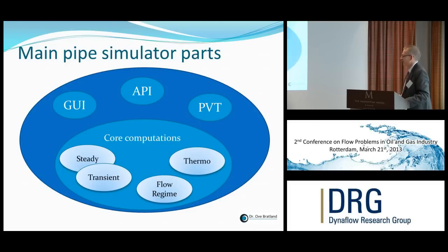It has to determine which flow regime they have, and that's what they are least good at, I think. It's difficult to do that accurately. Do you have slugs or not? Do you have stratified flow? What do you have in there? How does it flow in there? And they also handle PVT properties differently. They talk to third-party software, at least that's what Olga does, and take chemical properties from another software package. And they can have various graphical user interfaces also.